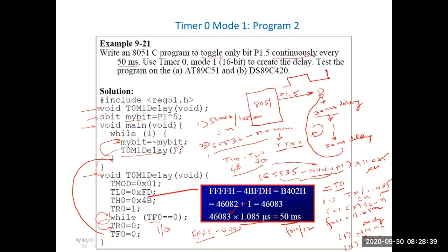again it will remain 0 for 50 millisecond, again 1 for 50 millisecond, again low for 50 millisecond, and this continues. So this part is 50 millisecond and this part is 50 millisecond. The time period of this square wave being generated here is 100 millisecond. If the time period is 100 millisecond, we can calculate its frequency. F will be equal to 1 upon 100 millisecond, which you can calculate.